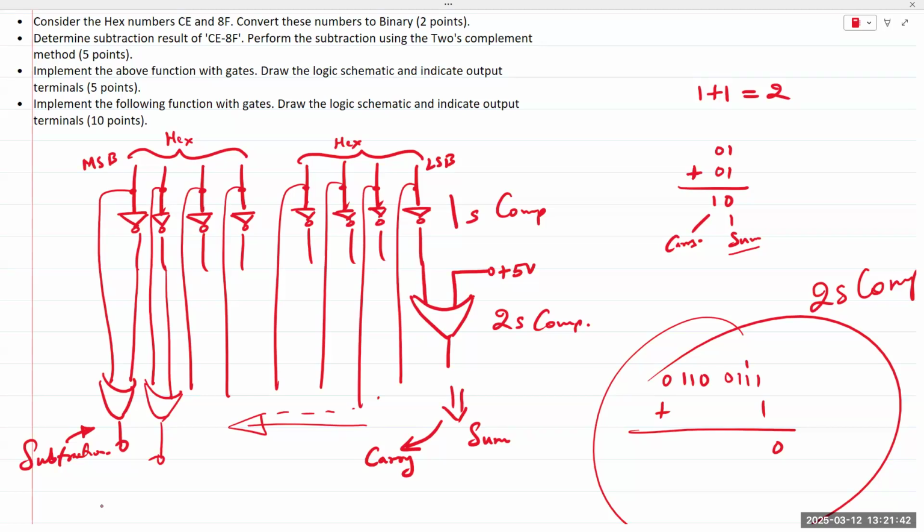You can do an online search and you can look up a 1-bit or a 2-bit adder circuit. It's implemented with at least 4 different kinds of gates. Okay, so like 2 XOR gates and 2 OR gates to account for the sum and the carry bit. And so once you have the carry bit, it carries over. Right, it carries over to the left.